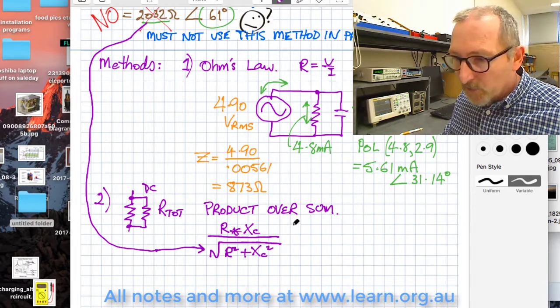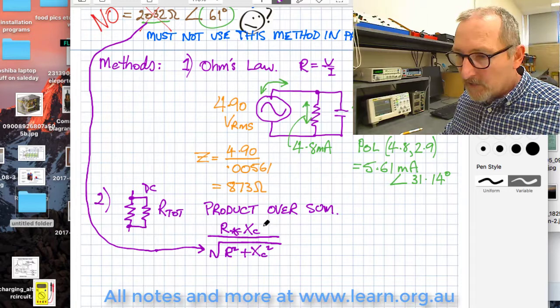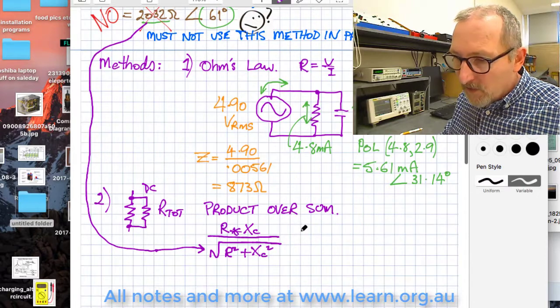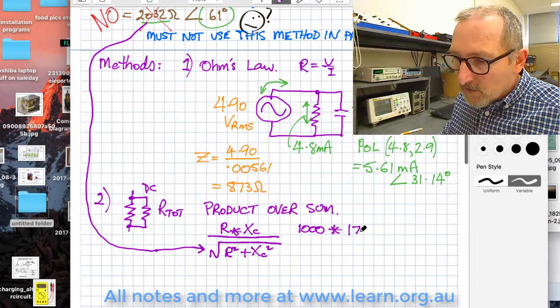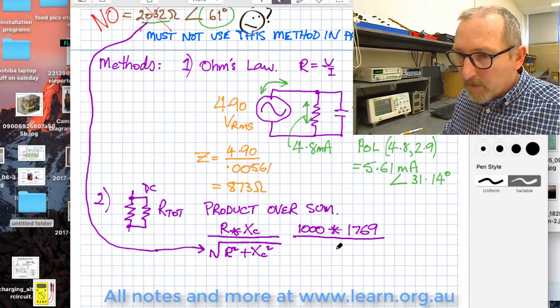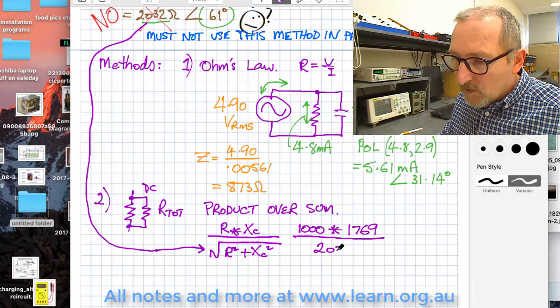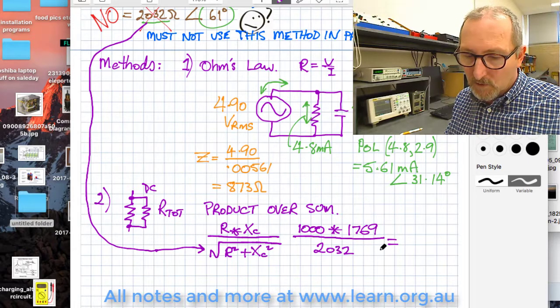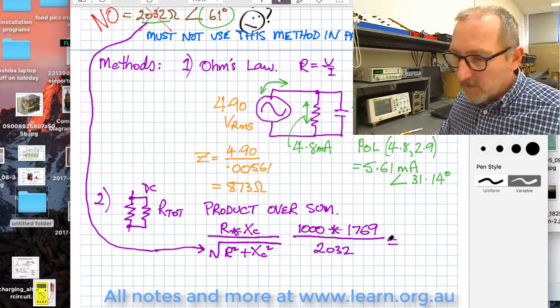So if I go ahead and do that, that would be 1,000 times, what was XC? 1769. 1,000 times 1769 divided by 2032 equals, he quickly punches some figures into his calculator, 1,000 times 1769 divided by 2032 equals 871 ohms.